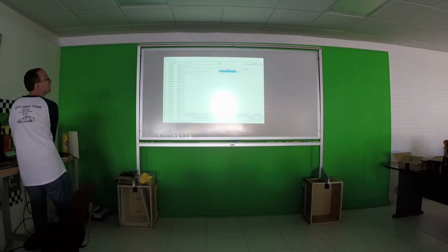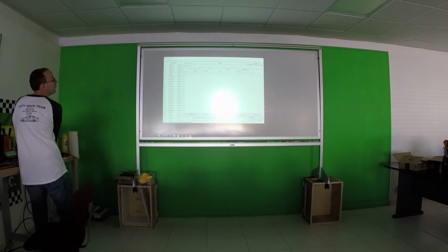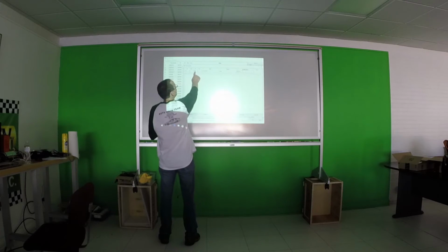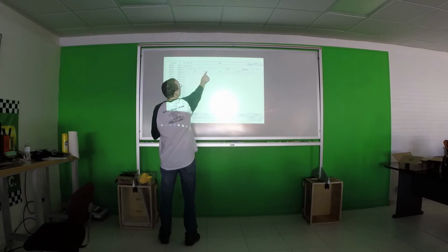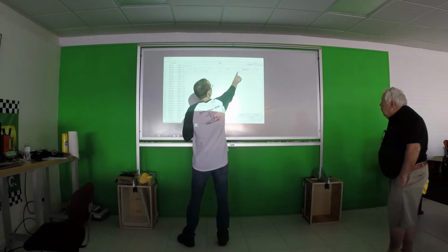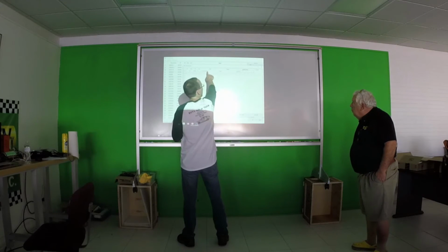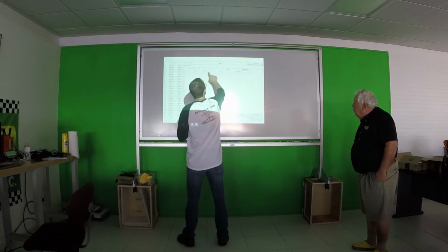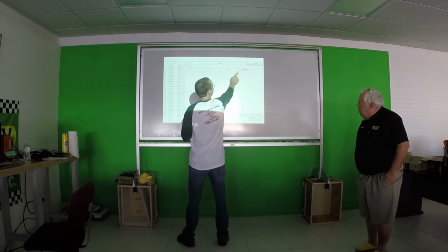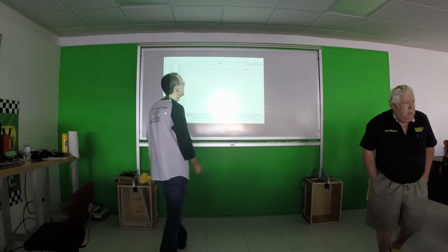What did you just do? This is a script here. What I've done is I'm saying that we're going to send a message 106. It's going to have 8 bytes of data. The bytes are 1, 2, 3, 4, 5, 6, 7, and 8. We're going to send it every 10 milliseconds. And the modifiers here means we're going to take this value 8, add 1 to it and send it. And the next time, 10 milliseconds later, we're going to add 1 to that again. It'll turn to 10 and send it. So you can kind of build counters that way.